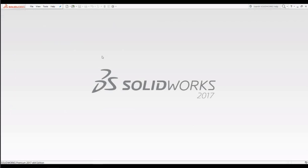Okay, first, the easiest thing we can do in SolidWorks is create a box. That's the easiest thing. So now we are going to do our first part. We are going to create a box. In order to do that, we have to open a new part file, a new part document. To do that, there are actually two ways. First is to go to the standard toolbar up here. This is the standard toolbar.